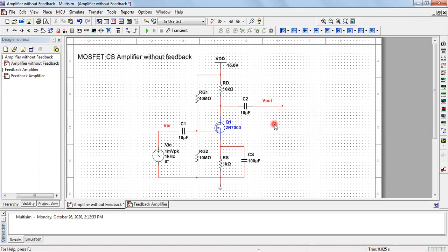Also, by running AC analysis, that is by plotting the AC response, the magnitude response, we can know how much gain we are getting. Clear? We all know we have already performed the transient analysis to find the amplitude and then the gain, and in earlier experiments we have performed the AC analysis also, to find the V out magnitude, which is equal to the gain. That itself is the gain. So you can find the gain either by running a transient or by running the AC analysis.